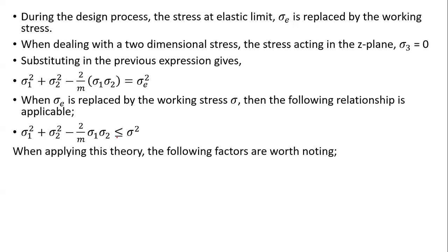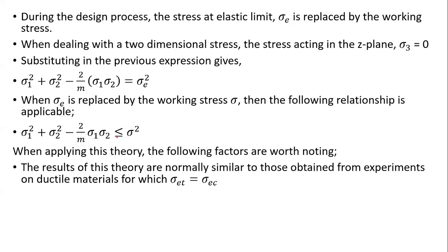Now, what factors do we need to note when we're applying the strain energy theory? Number one is that the results you may obtain from here are normally similar to what you get from experiments on ductile materials, on condition that the elastic limit stress in tension should be equal to the elastic limit stress for compression. If the two stresses at elastic limit are the same, then we can apply this theory.